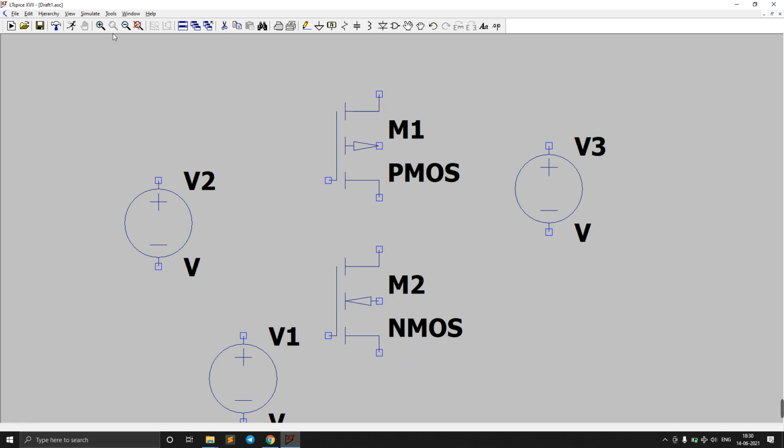So let's connect now. Here, instead of the resistor or the diode connected load, we replaced that with the current source load. So it ensures that we may get the maximum swing, and it will slightly change the linearity of the circuit. That means a little bit of non-linear behavior. So let's connect these things. We'll connect these, and from here to here.